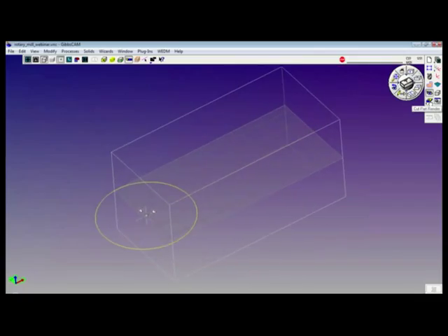All right. Once we've defined a workgroup as stock, we leave it alone. The rule is one stock workgroup per file. In this case, we've defined it. We've drawn geometry in it. Now we just forget about it. Our actual geometry to be machined is going to be built in an adjoining workgroup.